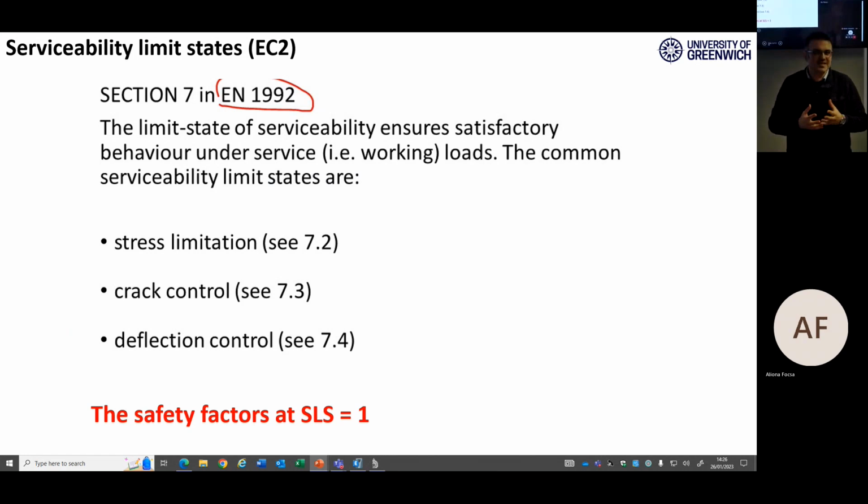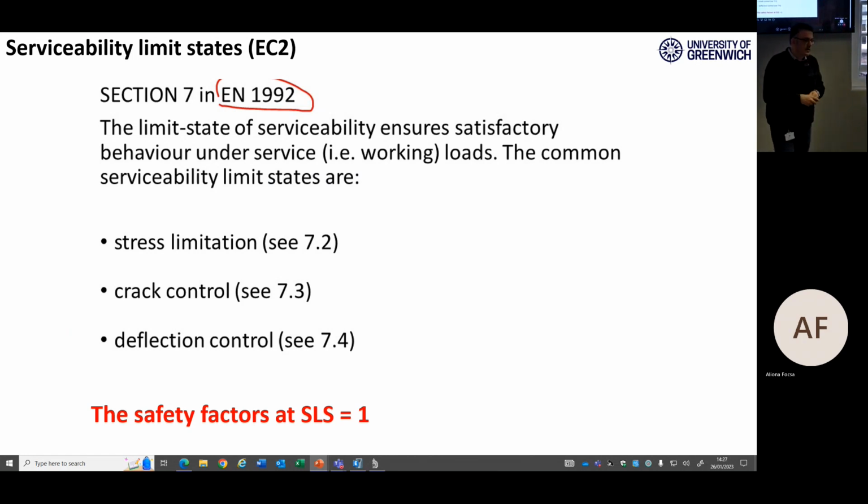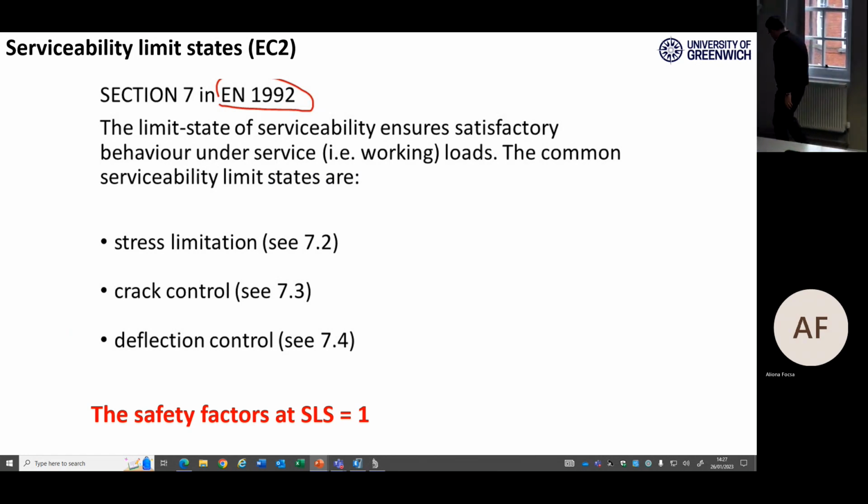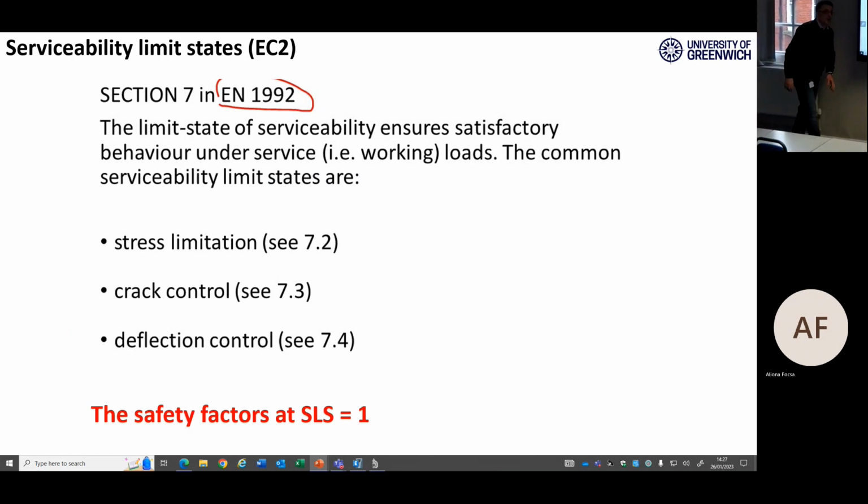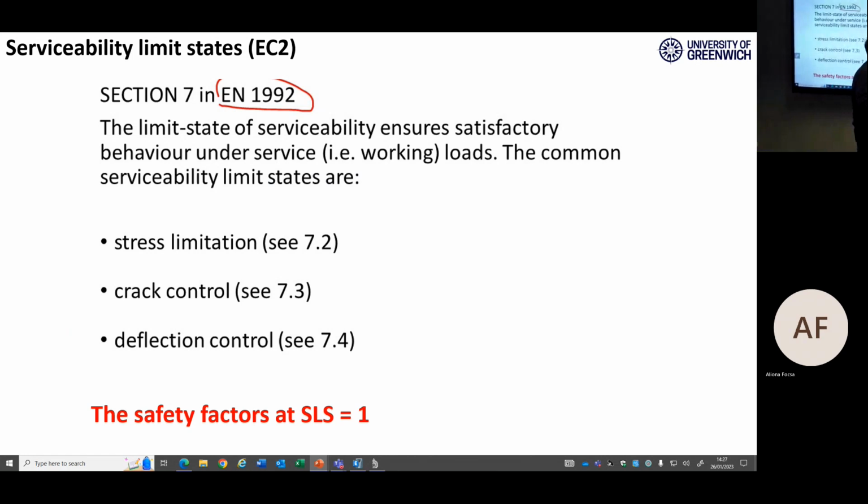In ultimate design, the structure is under all the possible loads that can be applied on it. The maximum possible load, live load with all the uncertainties, which means 50% more, is coming on the structure. And everything, earthquake happened, the most intensive wind is blowing. So all the possible loads are applied.